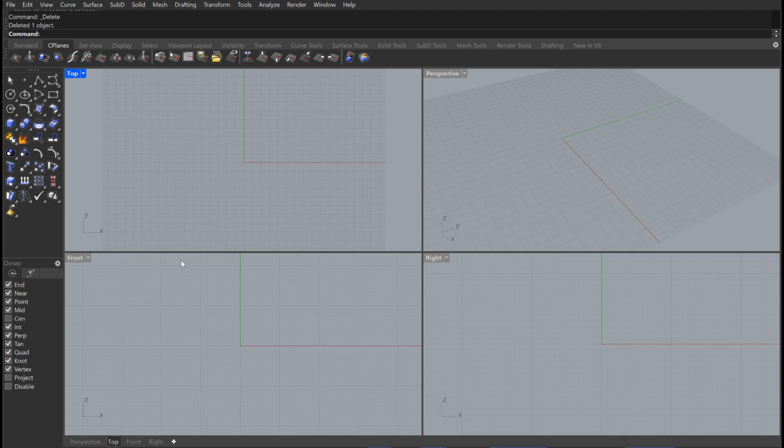Okay, now moving on, we have our rectangle. We will select our rectangle from here, or we can type it in the command bar. Instead of generically drawing our rectangle like this, if I wanted to define my measurements as all architects do, I'd press P over here to select the 3-point rectangle, and now it's asking me to define my width.